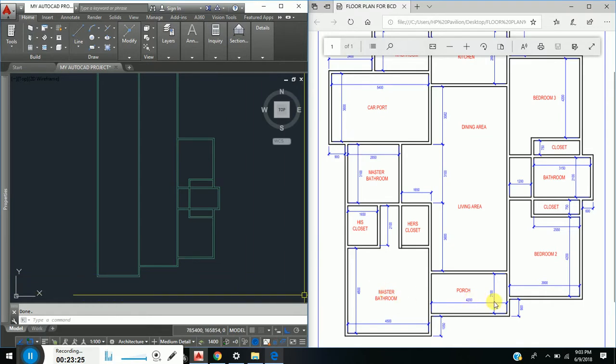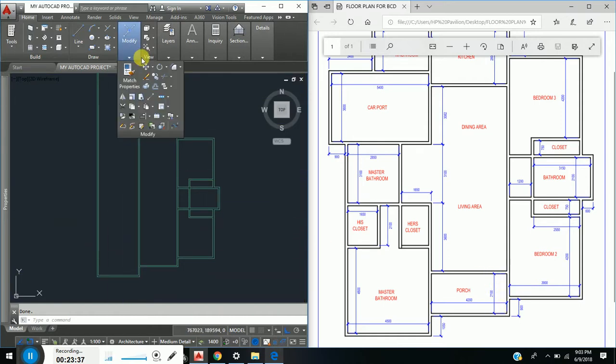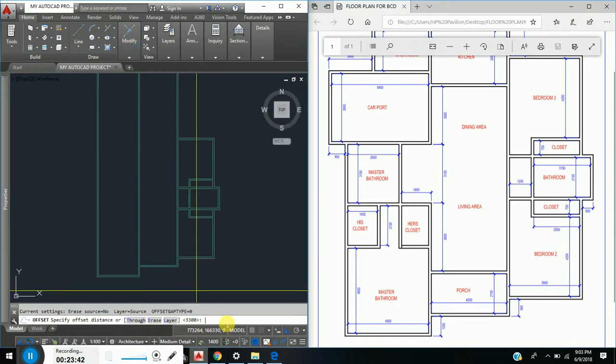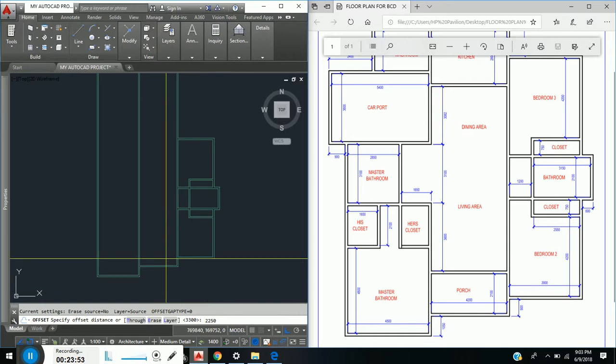I could just stop here and put the porch in, because the front porch has a depth of 2100 given as an internal measurement between two walls. And so I'm going to give an offset from my Modify. I give an offset. The distance when prompted would have been 2100 plus 150, so that's 2250 millimeters. Alright, and that is measured. Give an enter, and that is measured from this wall in this direction. There we would have had this wall serving as the porch.